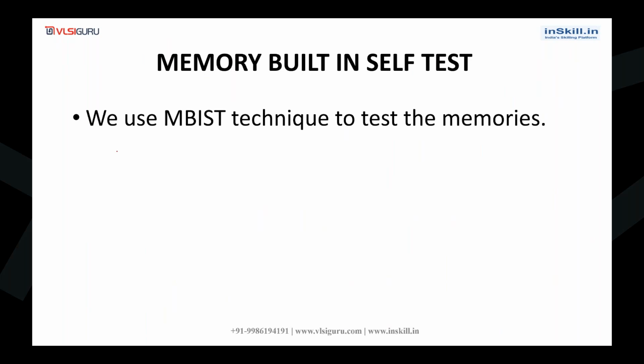We will cover the various memory fault models, like stuck-at fault model, transition fault model, address decoder fault, coupling fault, like that.